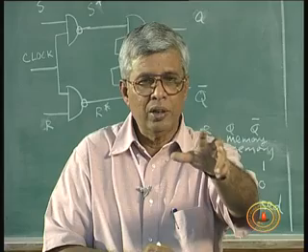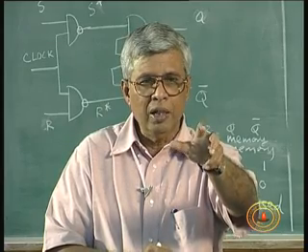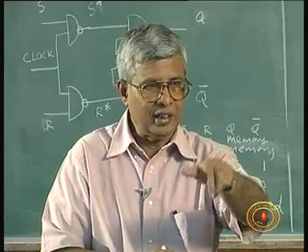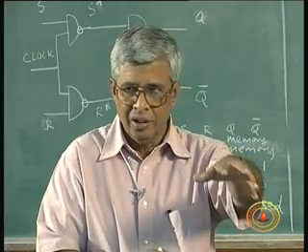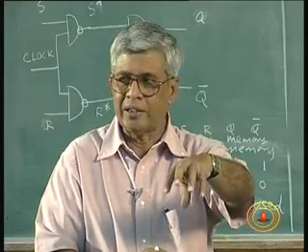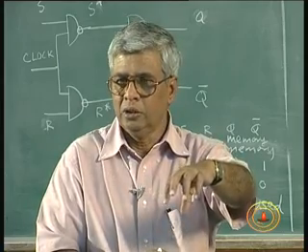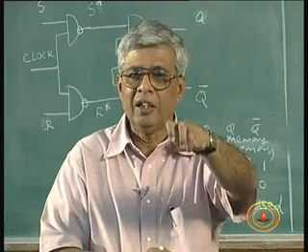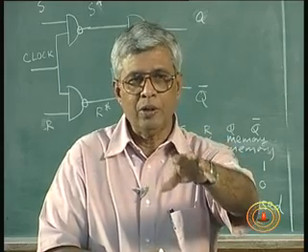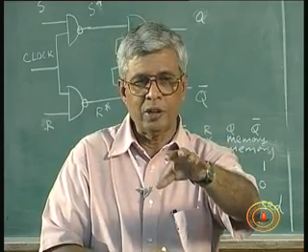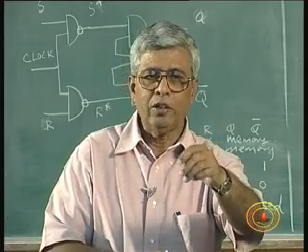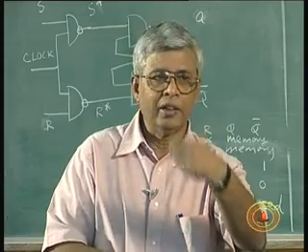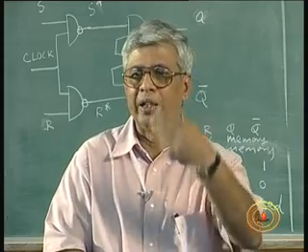So, the minimum period for which you allow the clock to remain high is the period the latch requires to process the inputs. So, the propagation delay, we talked about the propagation delay. The propagation delay of the flip flop is the time it requires to process. So, if you try to change your clock too frequently, too fast, and change the input also accordingly, then it will get confused. So, that is the highest speed I can work with.